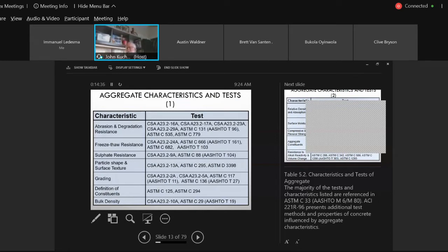So in other words, there's 6 different types of cement that you would use depending on what you're designing. Our pavements is general use, above grade, GU. Anything below grade, HS. And our levels can fluctuate from season to season, even across the construction site. You may be in one area where the sulfate levels aren't as extreme as in another. But Winnipeg is classified as very extreme concentrations of sulfates. So again, one of the tests you might do is actually in the soil, to determine sulfate levels.